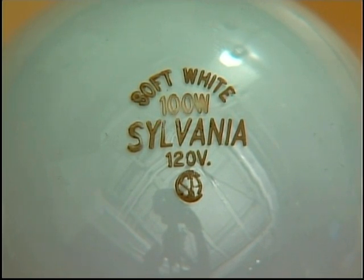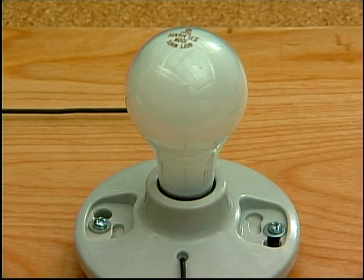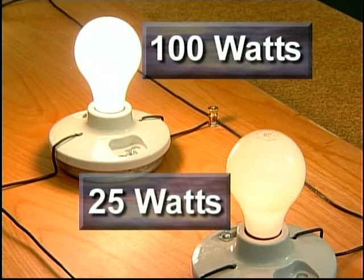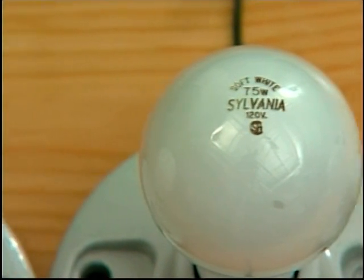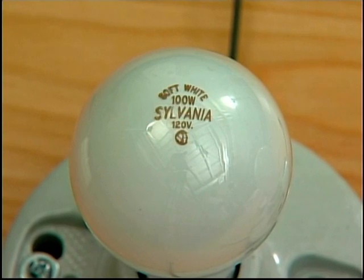The wattage rating of an electric lamp indicates the rate at which electrical energy is changed into heat or light. The faster a lamp changes electrical energy into light, the brighter the lamp will be. A 100-watt lamp produces more light than a 25-watt lamp. When using lamps that are rated at the same operating voltage, the wattage rating indicates the light output of the lamp and the amount of current it will draw.